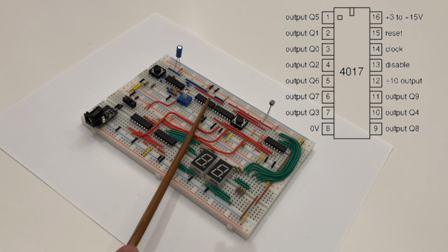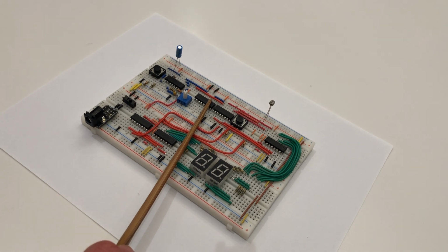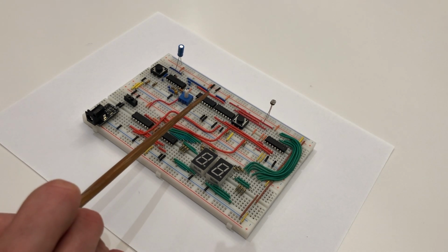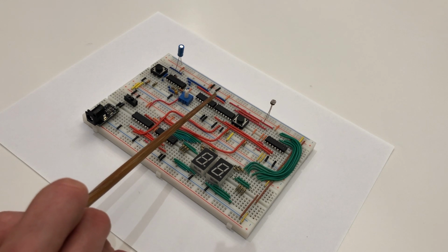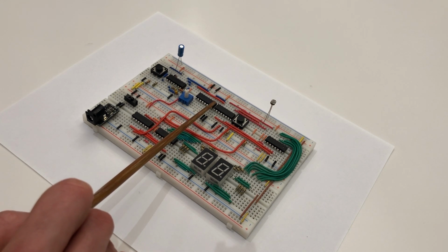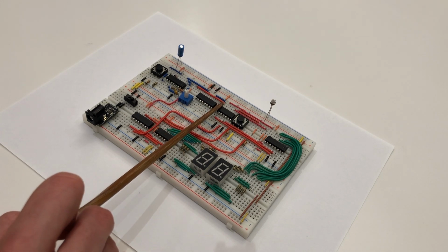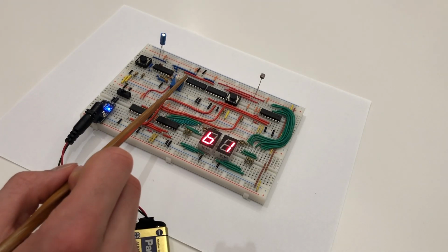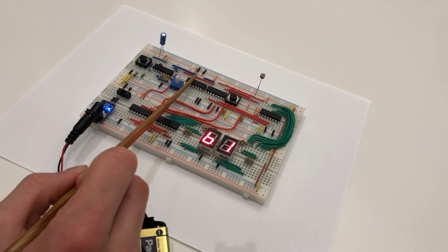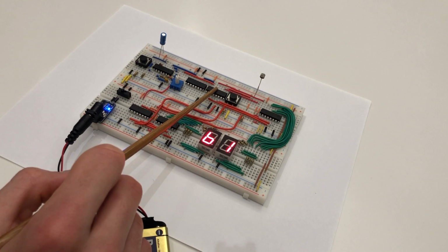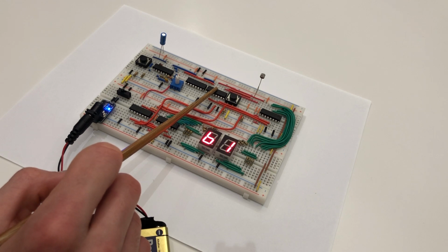Pin 15 reset and pin 13 disable need to be conditioned in order for this chip to function properly. If a pin needs to be conditioned, it should usually connect to ground or power, but different pins on different ICs have different requirements. In the circuit, the 4017 is only used to divide the clock signal outputted from the NAND gate oscillator by 10, because if the clock wasn't divided, the oscillation would be too fast, so the counting would be harder to observe. The clock signal from pin 12 of the 4017, which is the divide-by-10 output, is inputted into pin 15 of the 4510 in the counting circuit.